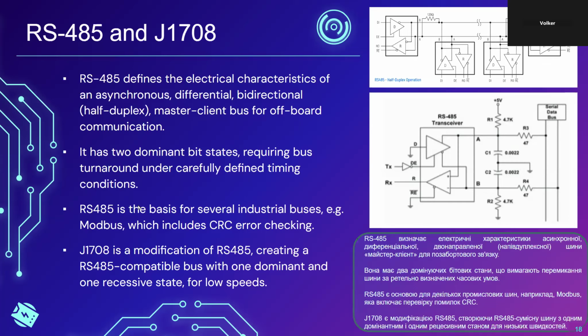It's a master client bus, so there must be a master. Usually the master is issuing commands and then either transferring data to a client or getting data back from a client. And it is intended for off-board communication. I probably should point out that the RS-485 drivers are very robust, and the maximum length of RS-485 is substantial.